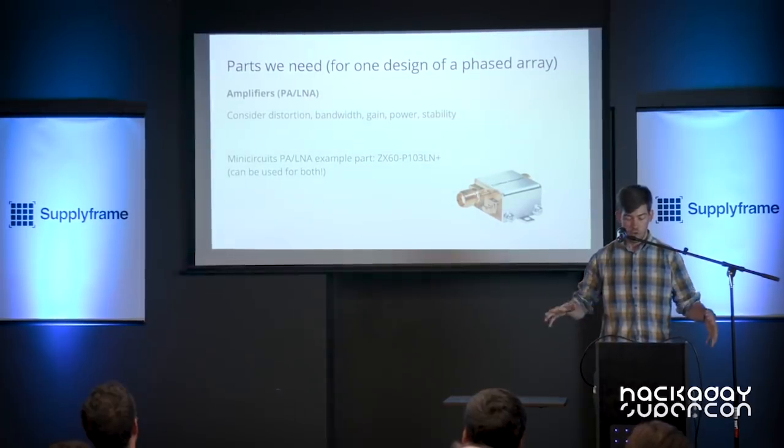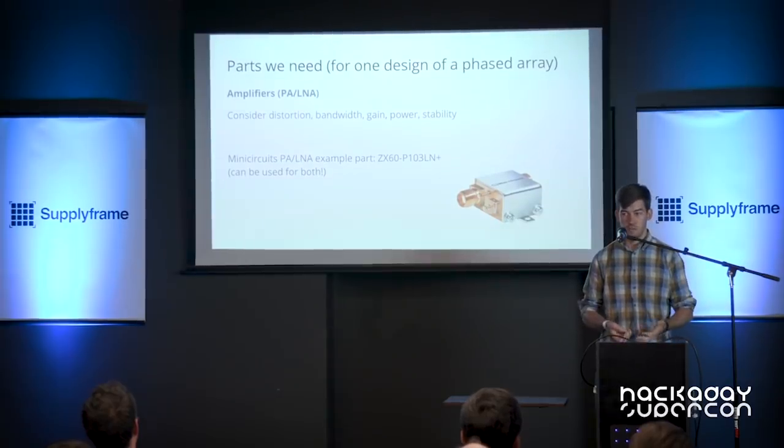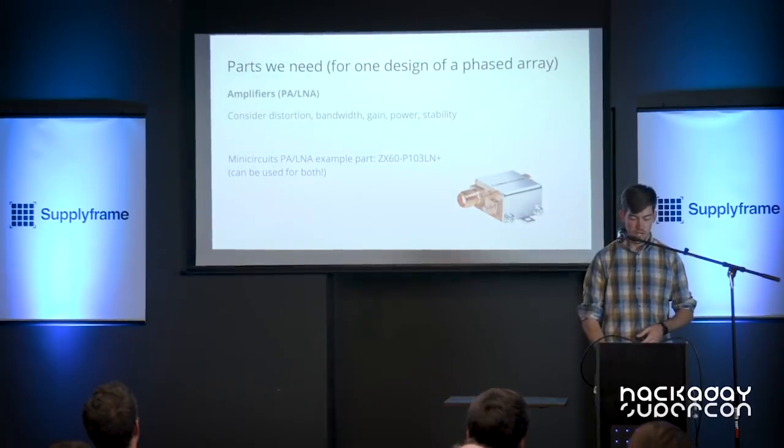If you string together this whole mini circuits thing that I've been showing parts for, you'll end up with an array that transmits at 2.4 gigahertz and outputs, I think, like 20 dBm or something. So it's not super high power, and for just playing around, it's fine.